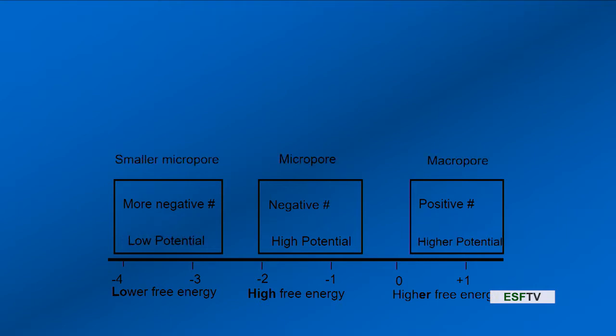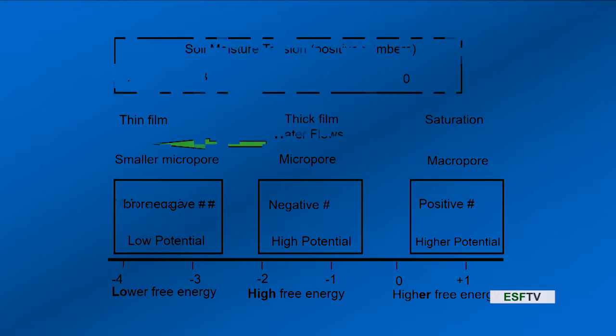We can also think about that in terms of the size of the pores, and water flows from large to small pores. And as pore size gets smaller and smaller, water will be drawn to those pores more and more. We can also think about that as films around soil particles, along with pore size. And we can think about water flowing from thick films to thin films.